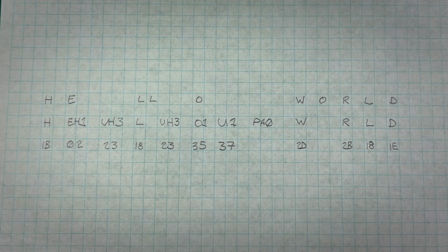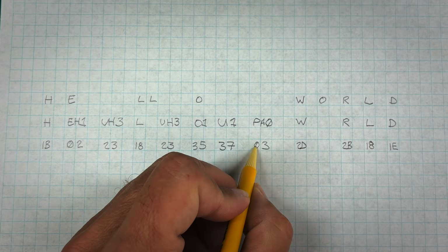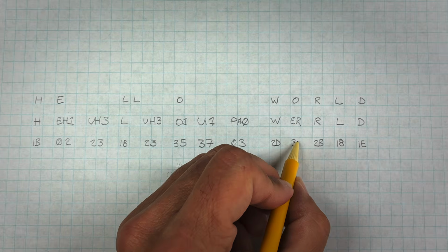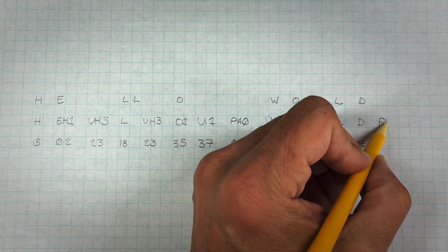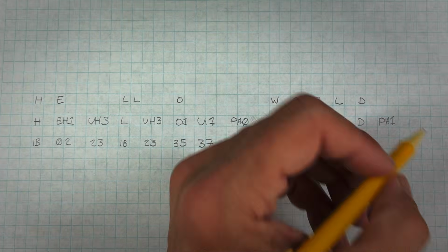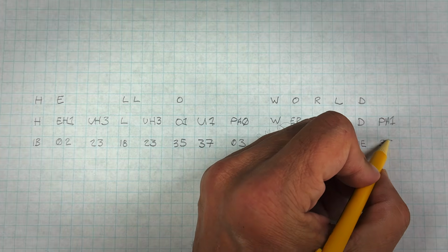It takes up time, but it makes no sound, and it's actually required for fricative sounds like T and K and P to sound correct at the ends of words. Its code is 03. And the O in world? It's not an O at all. World. It's actually an ER sound. Hex code 3A. We can put a longer pause at the end of world with PA1, code 3E.